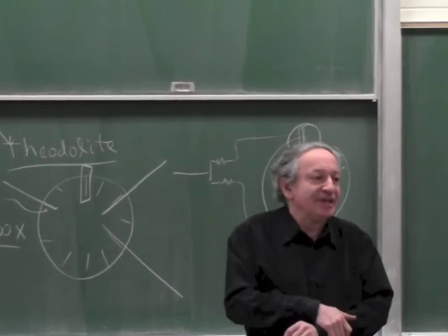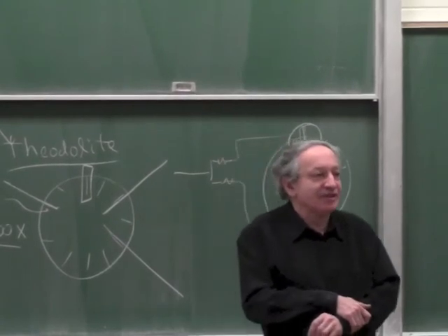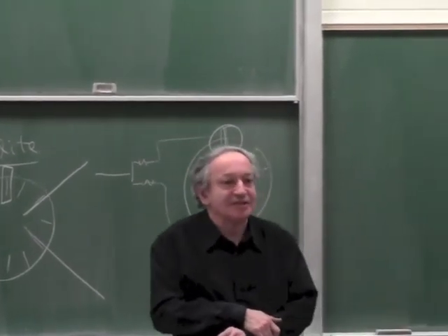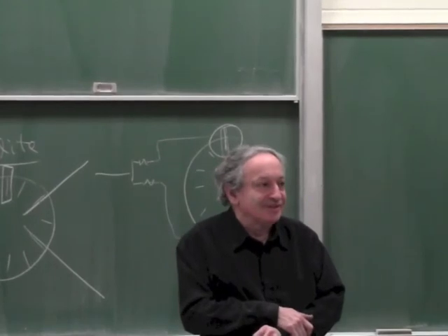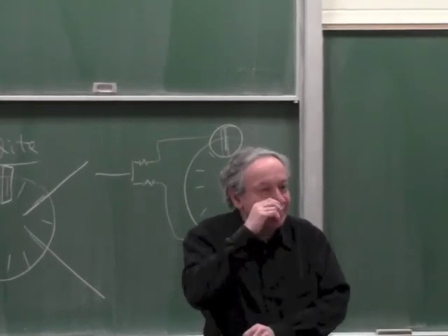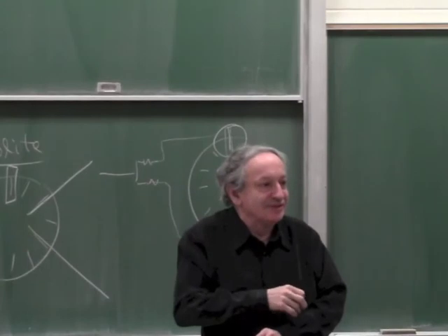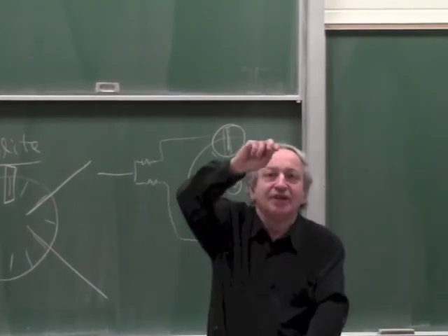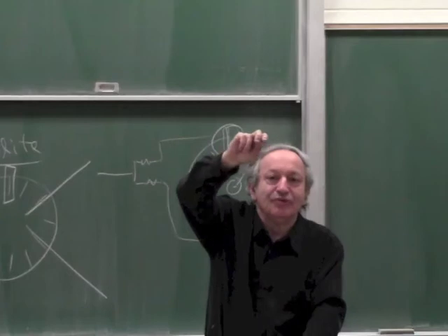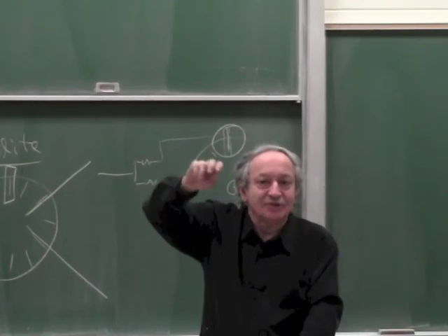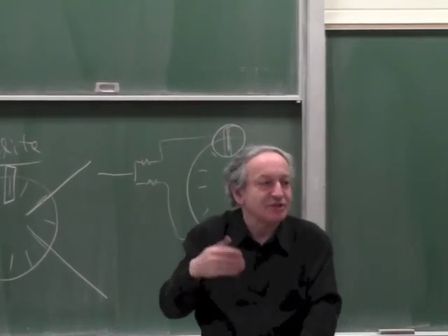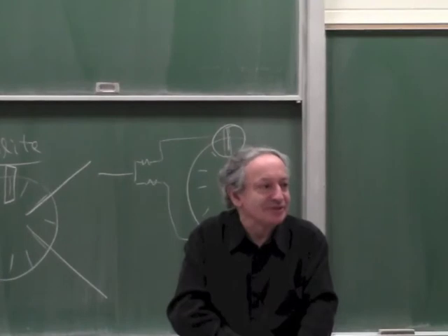So it's way too low a rate to do optical filtering because it's the same rate as the information. Unless you have a very slow-moving target, you can filter it by software. Let's say you're following a crane and you know the crane can only move a meter a second, so what the software does is average many frames to get rid of noise.